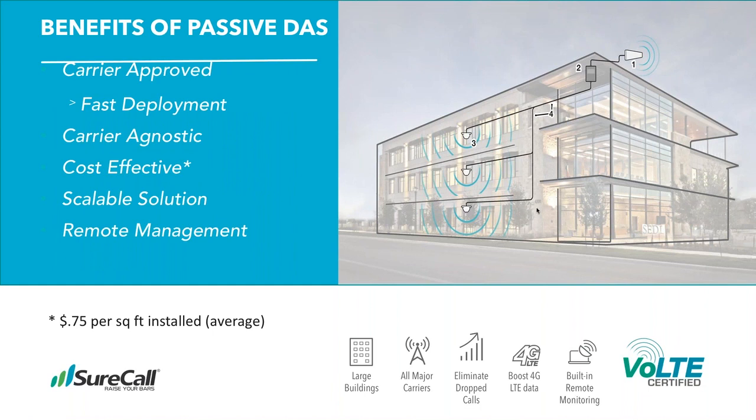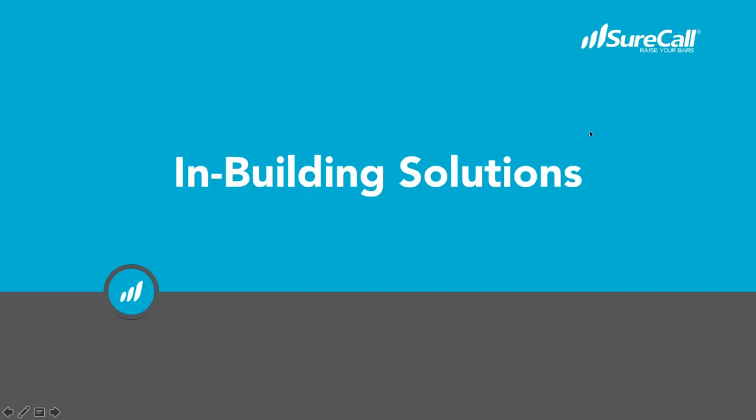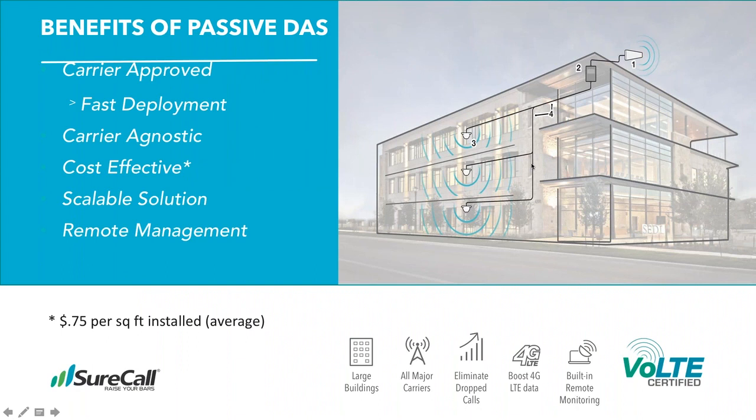So the benefits of the passive DAS, and you can see there's a picture there on the right-hand side of a building showing the antenna collecting the signal from outside. The amplifier is number 2, and then the signal goes through the connections throughout the building to those indoor antennas.